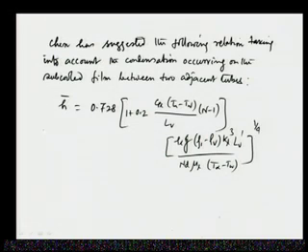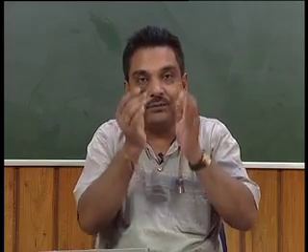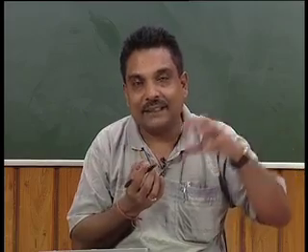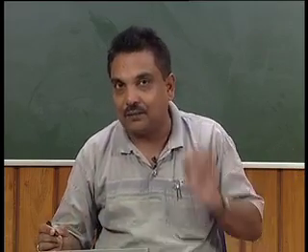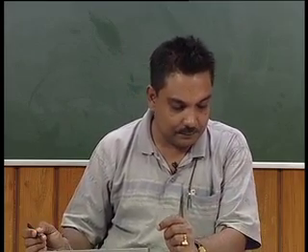In this case, n is equal to the number of adjacent tubes. So, we can understand this n is the number of adjacent tubes. This part is fine, and this becomes n minus 1 because of the fluid film there: if there are n number of tubes, there will be n minus 1 gaps, and in those n minus 1 gaps there will be some fluid film on which the condensation may take place. That is what is being given by this.